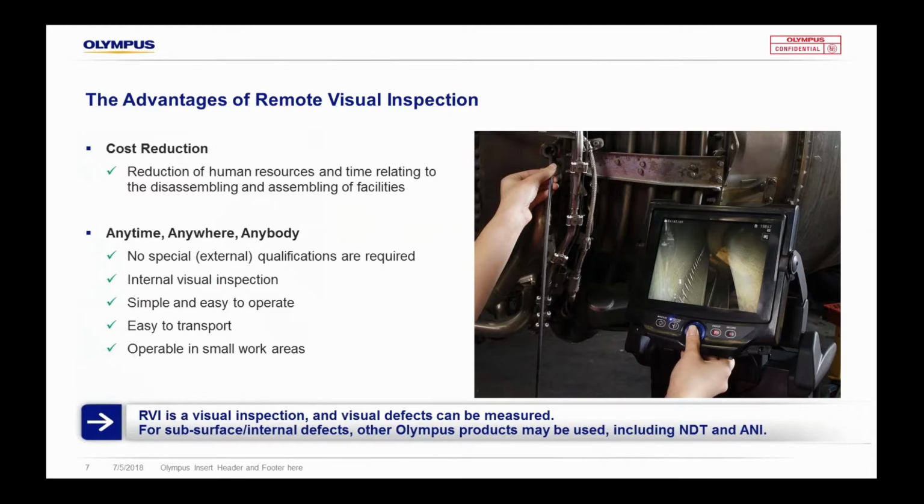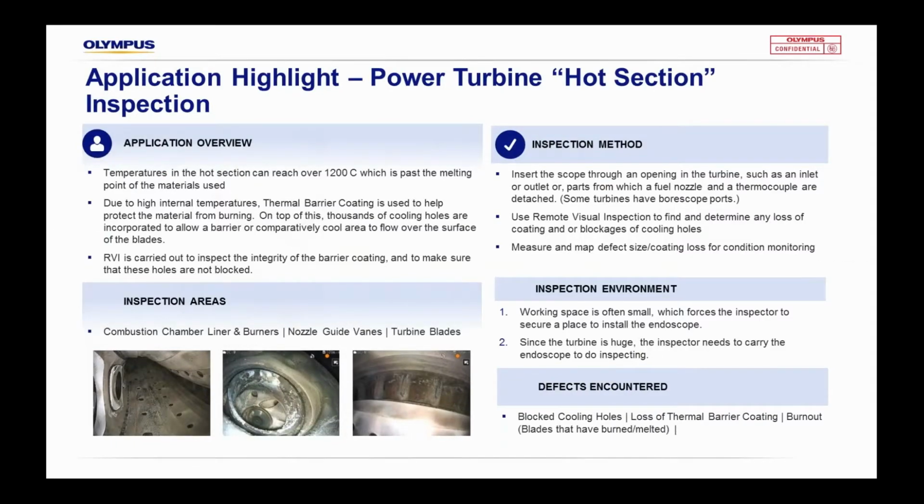It may be that you've got a reading of some wear materials in some product that explains that this could potentially be this part failing here. Then you can go in afterwards and check that specific part with remote visual inspection to see if that is the case.